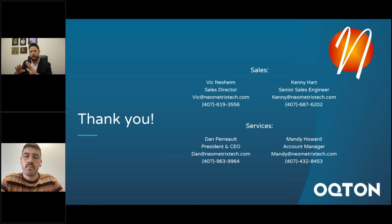Gotcha. Yeah. So on my DesignX overview slide, the scan is actually kind of sparse. As long as you have all the data you need to replicate the geometry, let's say on a revolve or a pattern feature, or even a surface, if you've got relatively most of it and there's a big gouge in it, when you go to model it, you can just ignore that area and utilize the surrounding geometry or geometry in another spot to replicate it. So it's a similar application. You only need to scan as much as you need to gather all the information and make sure you can place it correctly.